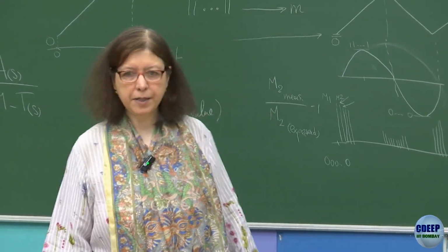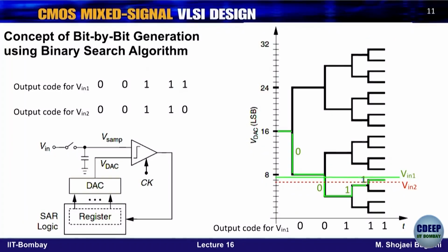Okay. So here, just to show one diagram. The green color, I have drawn two V-in values, two arbitrary cases. Just see, this is like a 5-bit ADC, and it eventually creates this kind of tree. It's like a tree diagram, really a binary tree. Every time you move from left to right, the ADC moves from left to right for the comparison purpose and generates bit by bit.